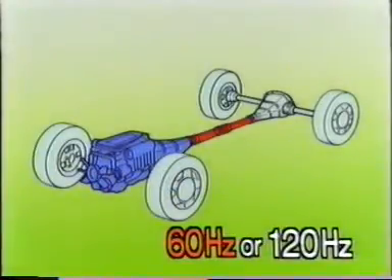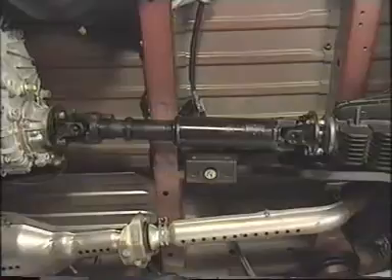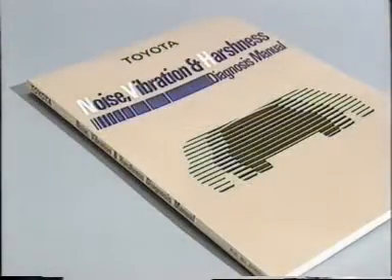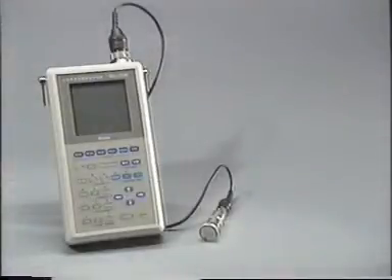We will now return to the case of the booming about which the customer complained. It appears that the noise is caused by something that rotates at the same speed as the propeller shaft. Or perhaps it is caused by the propeller shaft itself. We will check the balance of the propeller shaft, as it seems the most likely cause of the vibration. Please look in the NVH diagnosis manual to find the detailed inspection method to be used. Here we will only show the main techniques used in the propeller shaft balance inspection.